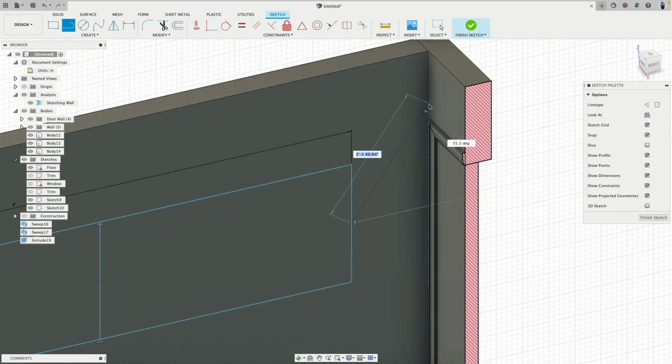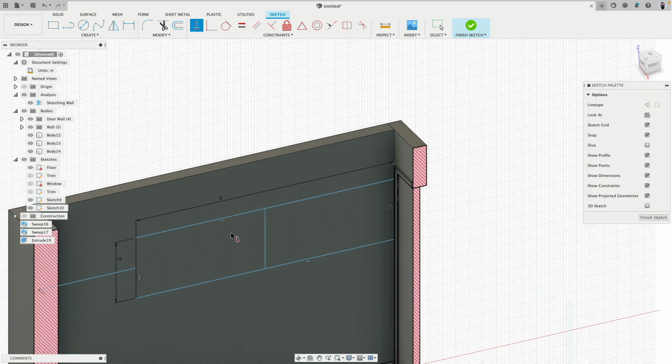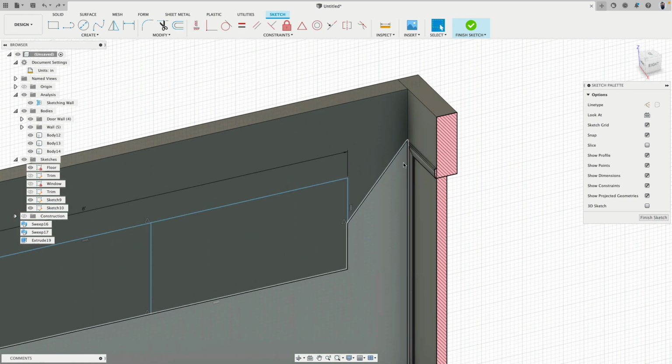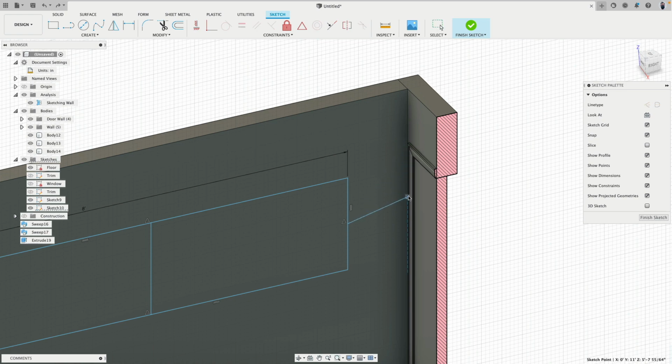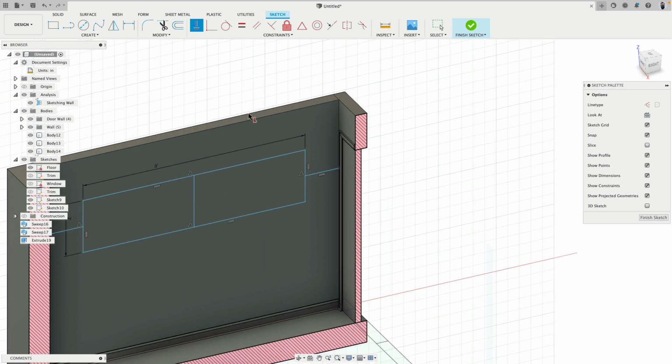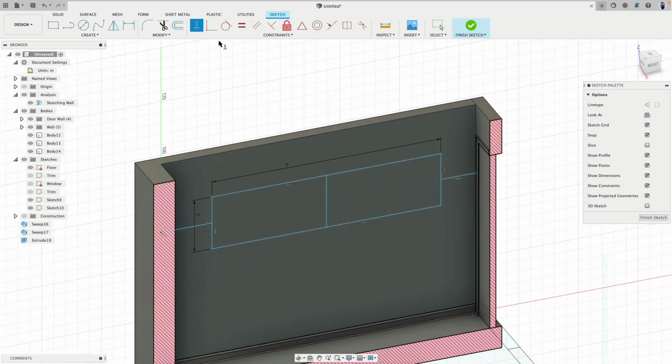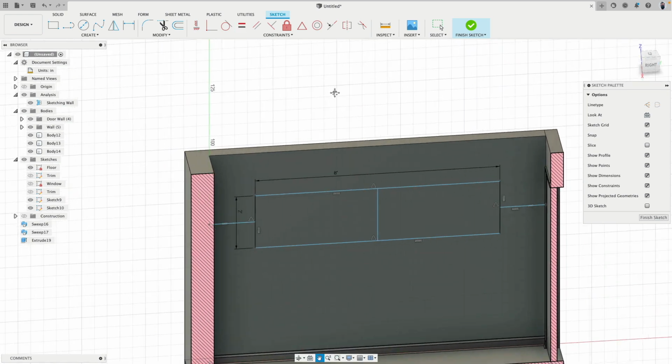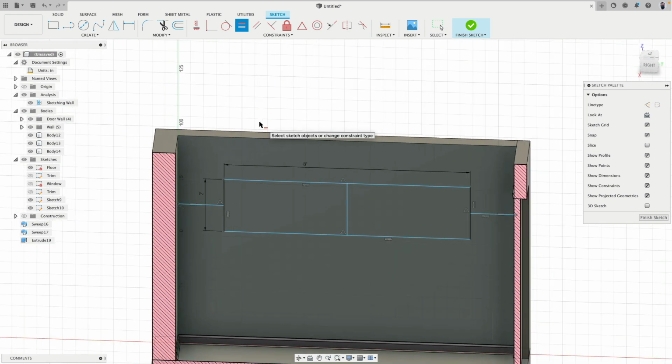I draw this at an angle, maybe like this, and I go then horizontally constrained, and that didn't really work out as much. Or maybe this point now I start dragging down a little bit more, and then horizontally constrained. Yeah, better. Both lines should be the same, so equal. Zack, done, finished. I don't need to measure the distances because it solves it for me.